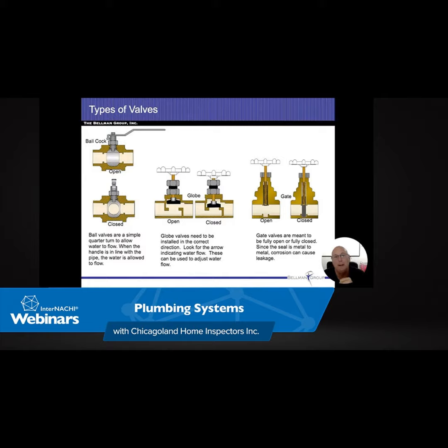Now, going back to my fireman years, there was something that the water department would complain about the fire department all the time. Once a year, we call it hush and flush. We would have to go out to all of our hydrants and open up the caps and flush all the water out of them and spray all the valves and the threads and the caps and everything with a little bit of lubricant and put all those things back together. But opening up those hydrants allowed a significant amount of water to flow, and then shutting them down created a pretty strong water hammer on things as well. So that would actually shock our pipes.